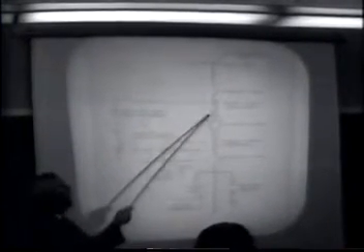We have the relay circuit, which we mentioned, which is fed by the bushing current transformers, and this bushing current transformer is a component of the circuit breaker. It is mounted on the bushings of the breaker, usually contained inside the tank of the breaker in the case of the oil breaker, and its particular function is to reduce the current that is flowing in the power circuit to a level that can be handled easily on your switchboards and in your circuits inside the control house.